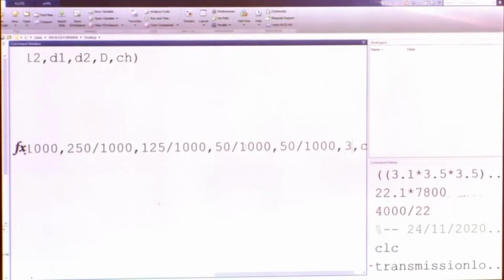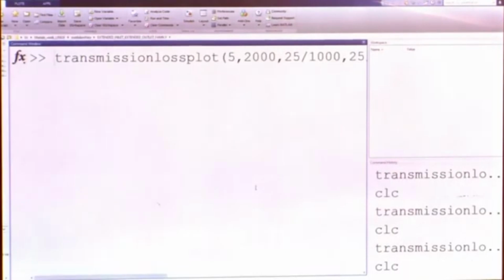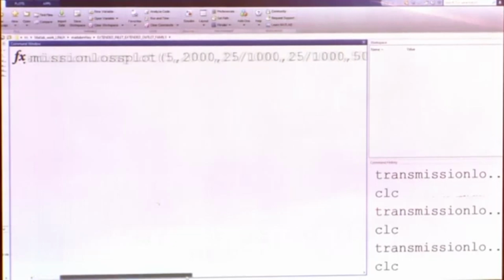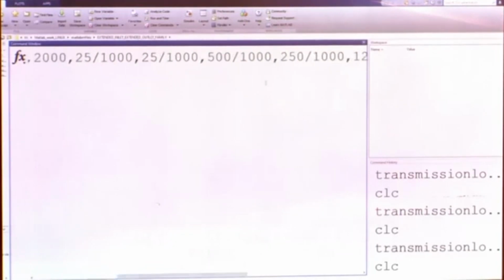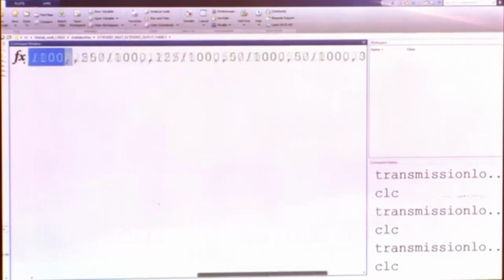Well, typically automobile mufflers have a maximum diameter of say 300 mm or 350 mm max. We will consider 300 mm, it can go from 150 to 300 or so, and this is just the color in which the graph will be plotted. So, we set the frequency parameters: 5 hertz is the lower frequency limit, 2000 is the upper one, 25 mm, these are the two at the inlet and outlet pipe extensions. These are the same as the diameters of the inlet and outlet pipe.